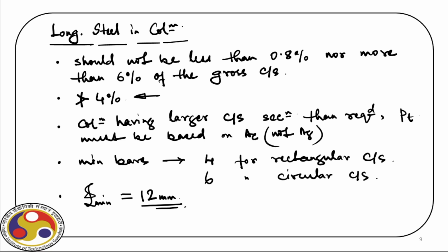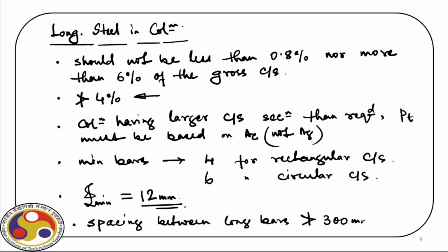Then, once we fix all these parameters, the spacing between longitudinal bars should not be more than 300 millimeter.